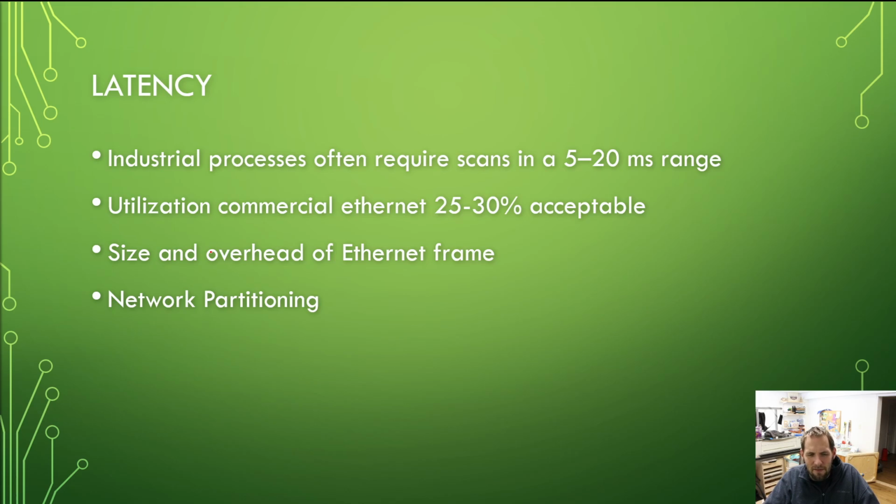Now that we're getting to the gigabit point with switching hubs and VLANs and things like that, deterministic Ethernet, deterministic real time, basically sending things saying this is a priority, needs to get there as soon as possible. This concern is overall not a big issue anymore, but it still is something that you do need to be ready to deal with at certain points, depending on the age of their network and the hubs and switches and things like that that they're using. If they're not up to the task, then maybe it's time to replace them.